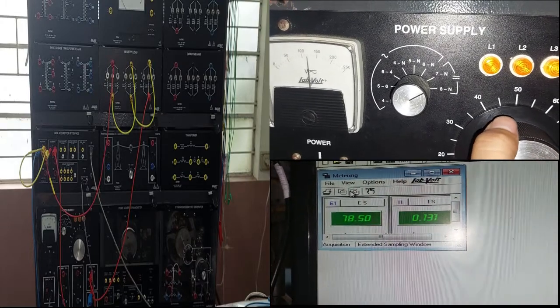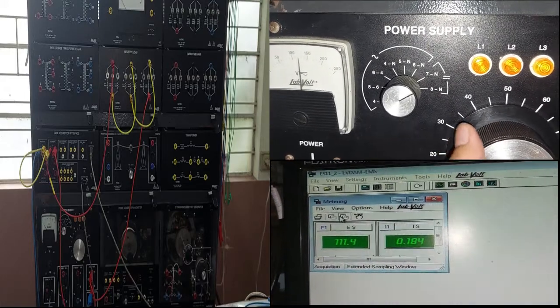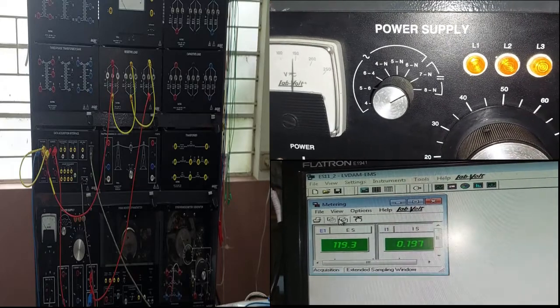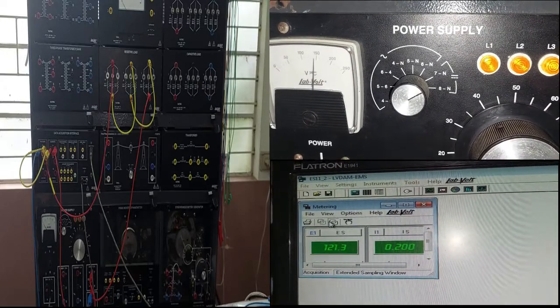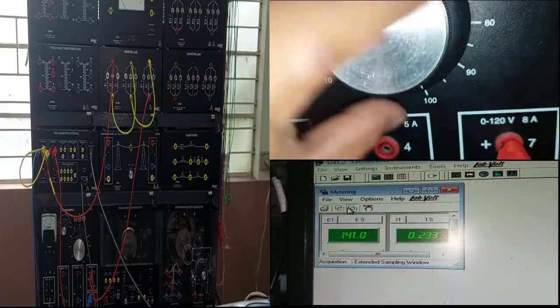Note that the values that will be measured by our ammeter and voltmeter will be used in order to solve for the resistance of the whole circuit, wherein we will use the equation V is equal to IR, wherein R is equal to V over I. After getting the value of our voltage from our voltmeter and our current from our ammeter, then solving for the value of our resistance through the equation V is equal to IR, we may now verify if the value is approximately equal to the value that would be measured by our multimeter.